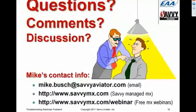All right. Radio noise issue here. Alan's asking if ignition noise would appear on both radios. Their primary radio, a GNS 480, occasionally gets a popping, boiling sound of interference. It doesn't matter who's talking, air traffic control or other aircraft. When it happens, they can switch to a number 2 radio, which is an MX11, which is clear, but not integrated into the 480 flight director. After a while, they can switch back to the 480, and it'll be clear. He was told that it was probably moisture in some connection. Now, the airplane's kept in a relatively dry hangar, and the last several flights they were in clear air.